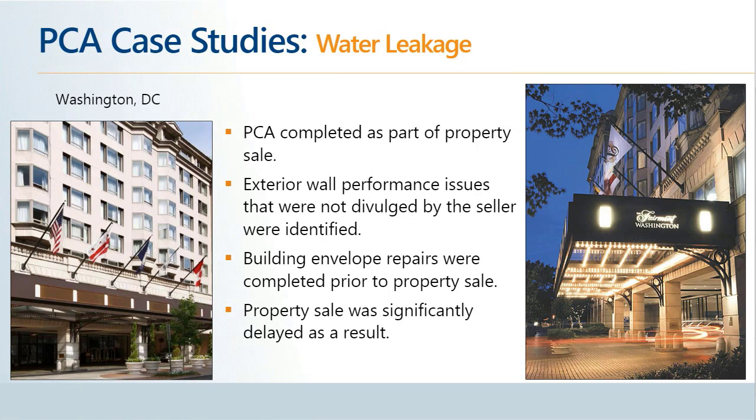They had another consultant on board that was performing a fairly detailed assessment of exterior wall performance, specifically an investigation into water leakage. That investigation, as I mentioned, was ongoing and included access to the exterior of the building, close-range visual surveys, and water penetration testing, all things that George mentioned as being items typically done during a more comprehensive assessment and omitted from this type of PCA.